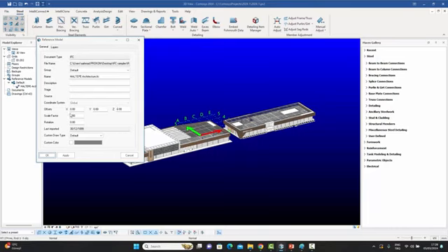You can also give a scale factor. For example, if you imported by mistake using the wrong units, say it was supposed to be millimeters but you imported it in centimeters, then even after importing, you can change the scale as well as the rotation. It also gives you information on when this file was last imported. So if the IFC file changes in the folder where it resides, you can re-import it from there as well.